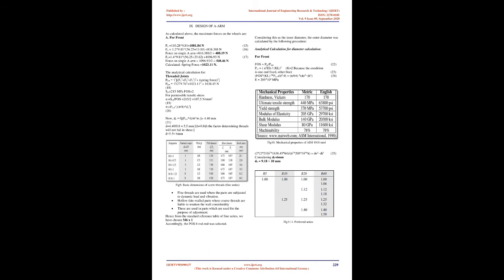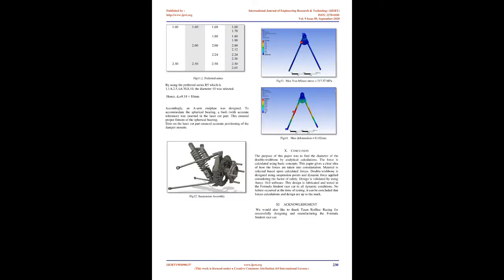Suspension assembly. Objectives. 1. A lot of forces during cornering, acceleration, and bump are applied directly during dynamic conditions, so it is essential to produce a compact, lightweight, and reliable suspension system to increase vehicle performance. 2. To reduce the unsprung mass. 3. Combining analytical calculations result with FEA as it provides a good starting point for the design. 4. To understand how much of an advantage FEA gives during the design process, it's first necessary to understand how analysis and design optimization are performed without FEA.